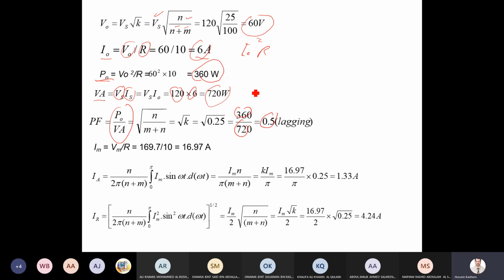Usually this circuit has low power factor. Sorry, and losses are high. So this circuit is useful mainly for applications where the load is not important to consume I square R or V square over R. What does this mean? It's preferable to use it to control induction heating, for example, an oven. But it is not that preferable to be used for controlling a motor.